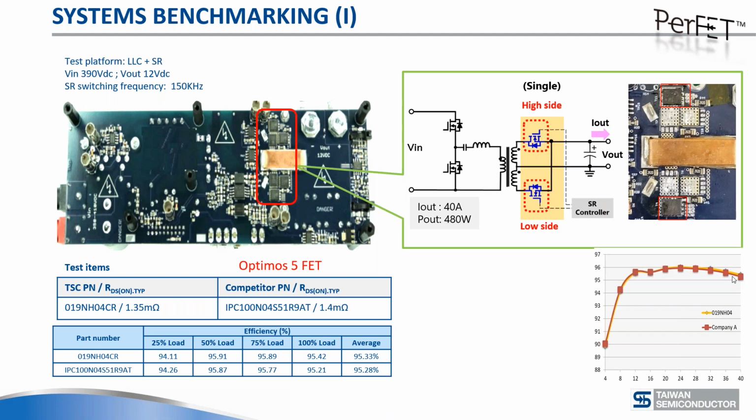So there is a wide spectrum, and you have to look at all the load conditions, because if you go to the low load condition, the efficiency goes down because the switching performance, actually the switching losses, stay more or less the same. It's the conduction losses that only go down. So that's why your efficiency goes down here. So we think this actually proves that we're doing relatively well versus OPTIMOS 5 in this case.